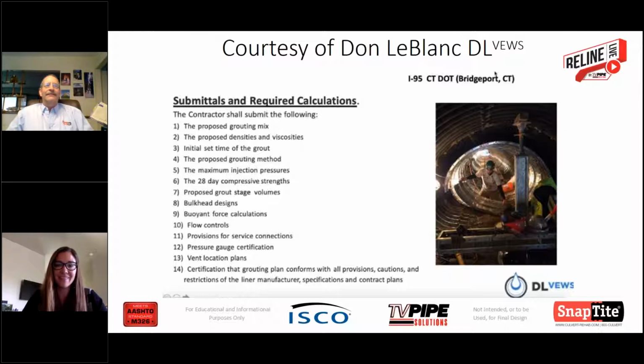Again, how long the grout takes to set up is going to be a function of the formulation or the mixture that you use. And typically, grouts will begin to set or begin to provide structural support to the liner, where it's not in a truly fluidic nature but more in a semi-solid nature, within 3 or 4 hours. Generally, when you pour concrete, you can walk on it within 24 or 48 hours afterwards. So it obviously has a lot of set and strength properties just in the first 24 hours.